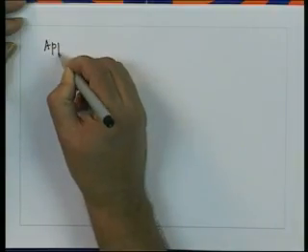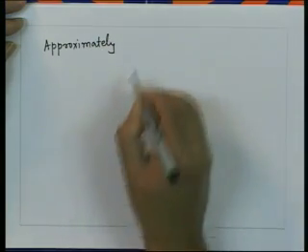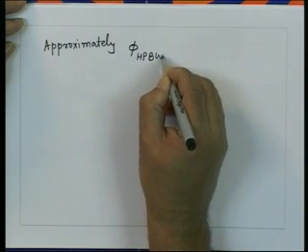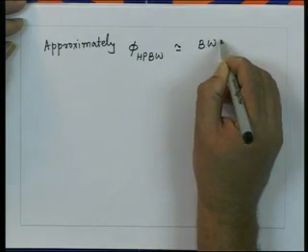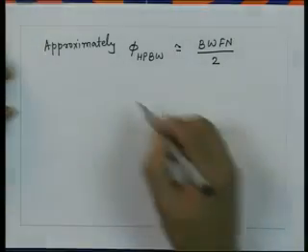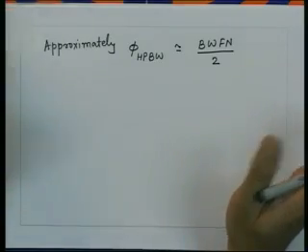So, approximately, the half power beam width is equal to the beam width between first nulls divided by 2. Now, if I have a radiation pattern, my job is essentially to find out the directions of the nulls. From there I can calculate the beam width between the first nulls, and half of that would be approximately the half power beam width.